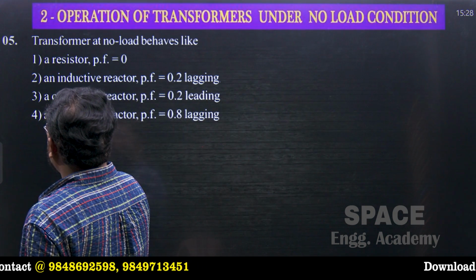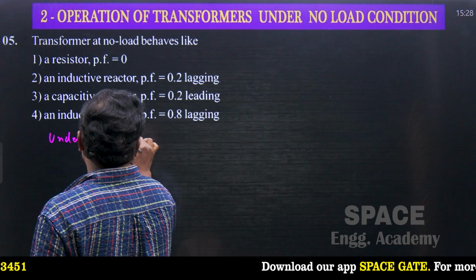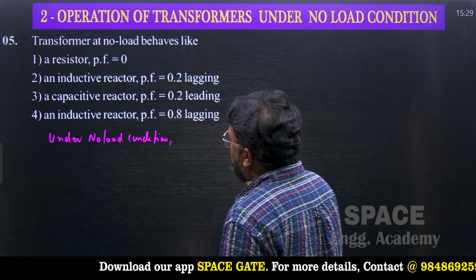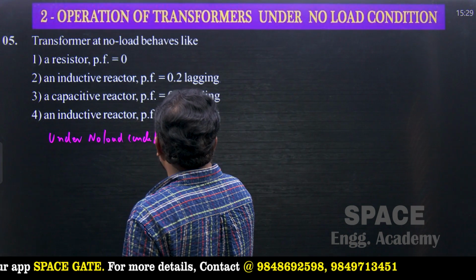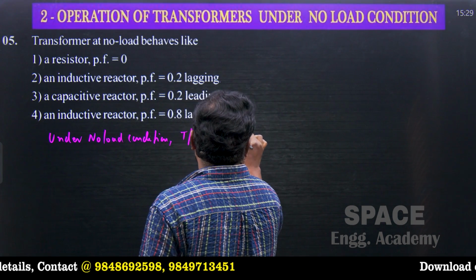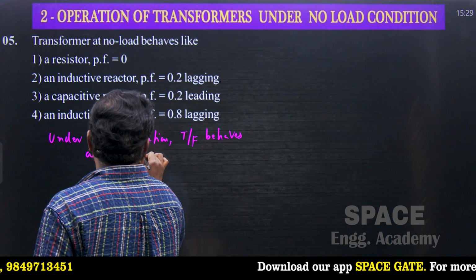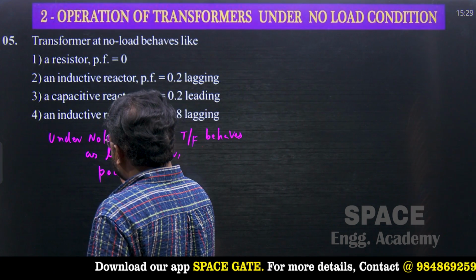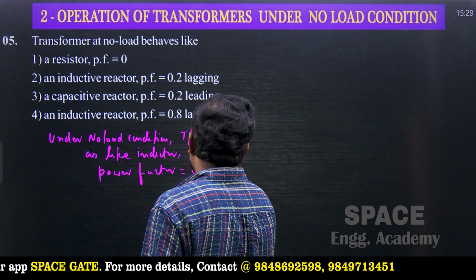So under no load condition, the transformer behaves like an inductor, and the power factor under no load condition is 0.2 lag.